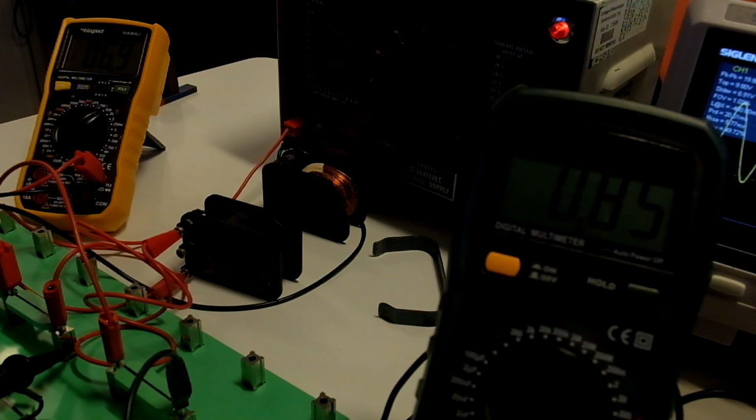To work out the voltage across the inductive part of the coil, we will use Pythagoras' triangle. So we take 6.9 squared, minus 5.355 squared, take the square root, and we get a value for the inductive voltage of the coil of 4.35.